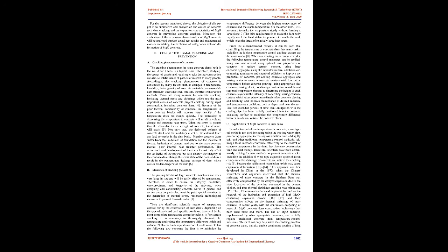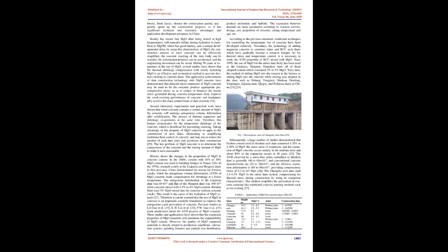and curing the concrete surface, which takes place immediately after concrete placing and finishing, and involves maintenance of desired moisture and temperature conditions, both at depth and near the surface, for extended periods of time. Heat dissipation with the cooling pipe has been partially positioned into the concrete, insulating the surface to minimize the temperature difference between inside and outside the concrete block. See application of MgO concrete in arch dams.